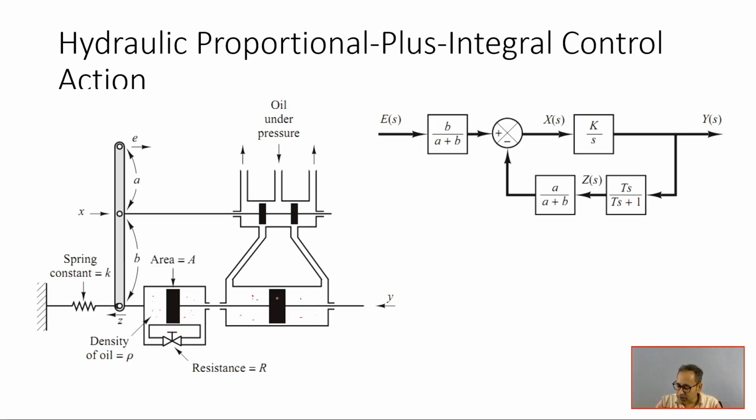Note that this power piston spool has rods at both ends, the same rod passing through. Here, the spool rod is connected to the dashpot at only one side, and the other side is not connected. Just notice this arrangement. All other things are the same.